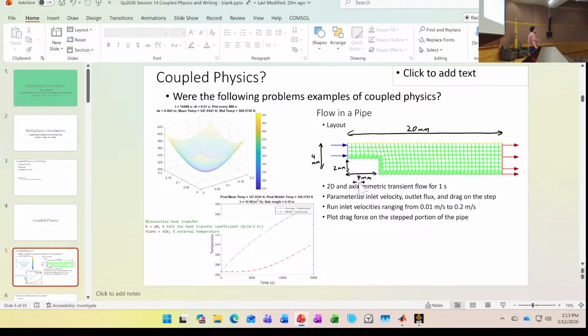Yeah, heat flux. Heat flux in. Or we could say it's 0 there, the first derivative of the temperature with respect to time or space is 0, and so that means that if that heat flux is 0, that's an insulating boundary.